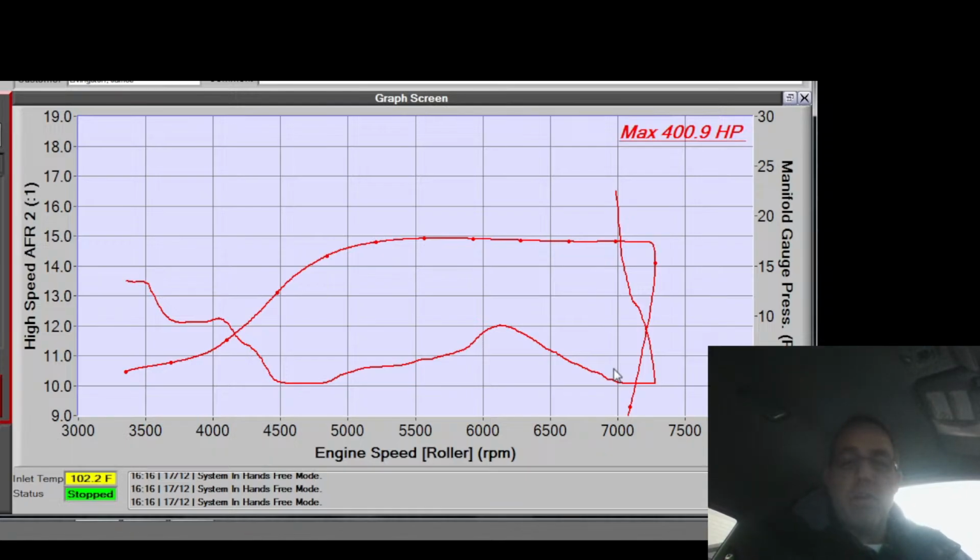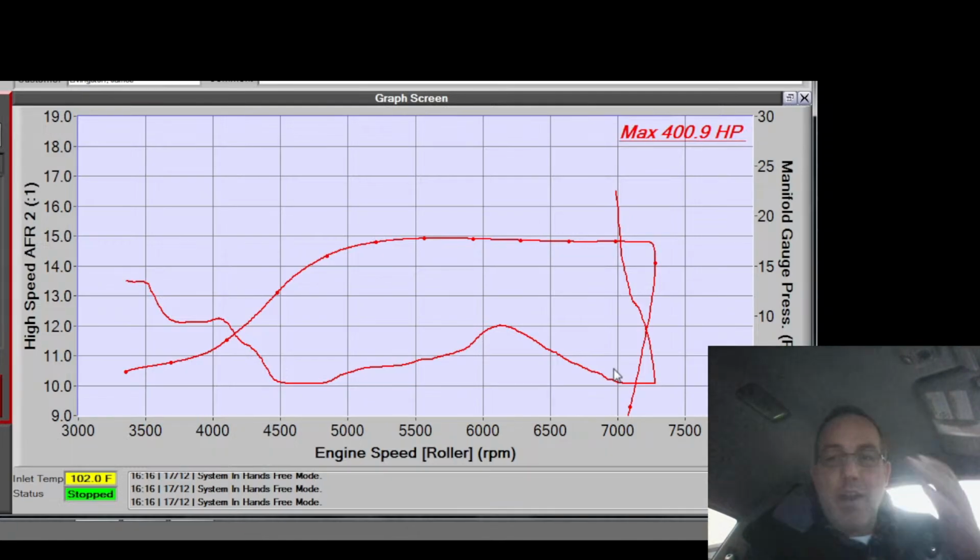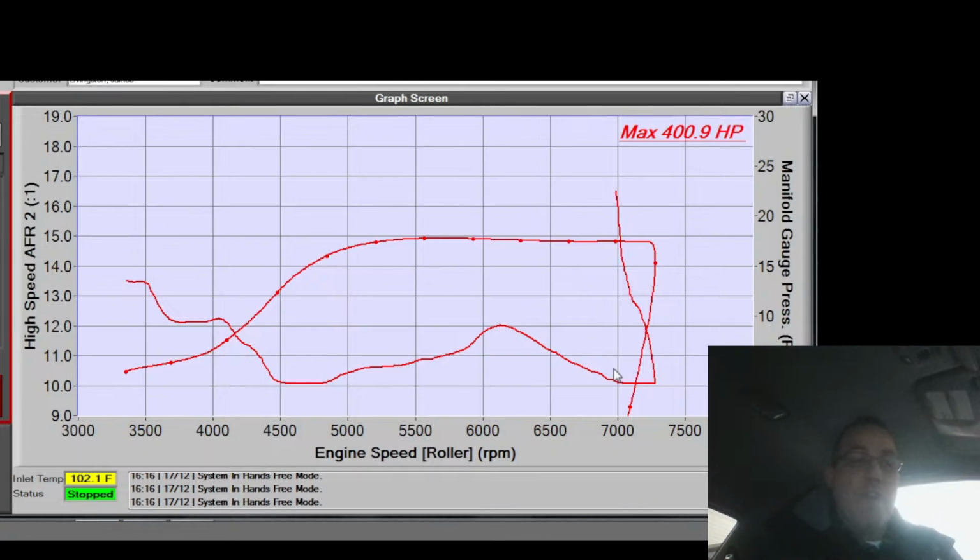A lot of guys go, oh, go to a cold plug, reduce knock. I'm like, how? What is it going to do? You're going to have it ignite twice? That's not what knock is. Knock happens after the initial combustion event begins. It happens because we've added enough energy, in the form of both heat and pressure, to ignite the other molecules somewhere in the cylinder, based on wherever that localized area is. And all we're doing is, if you took a reactants and products energy state graph, if you've ever seen those, it looks kind of like this dyno graph, really. Only there's a step missing out of this.